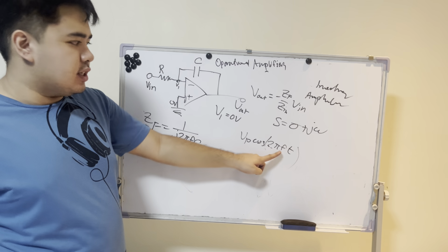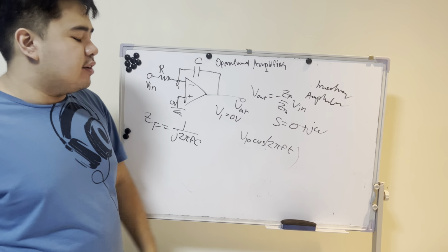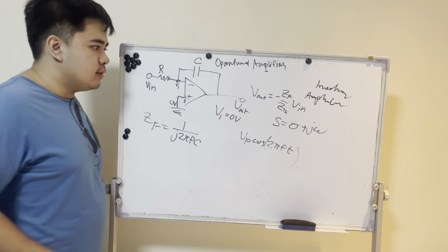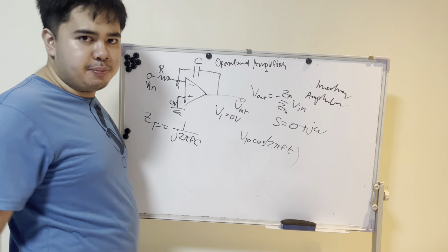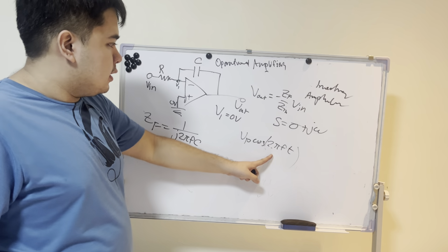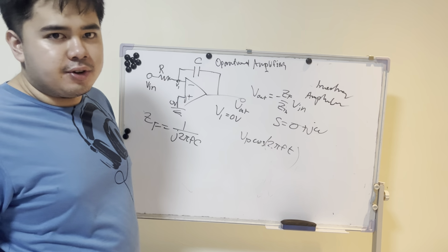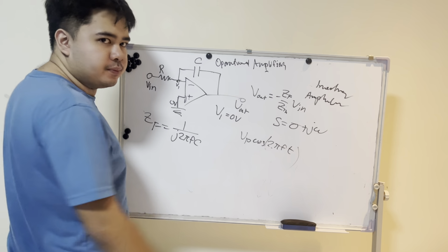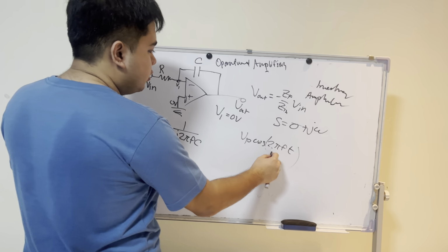This is the radian frequency. f by itself is just the frequency. 2 pi is because of the unit circle, or because cosine repeats every 2 pi, and sine repeats every 2 pi. So 2 pi is what we call the radian period. We multiply it by frequency in order to get the radian frequency times time. That becomes the input for this one. We usually shorten it to omega.